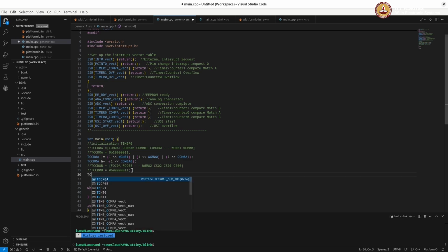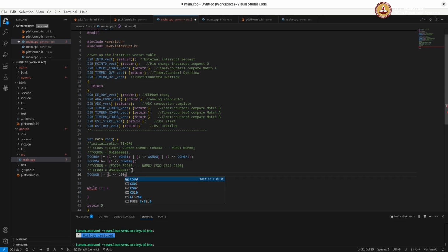So let me write TCCR0B. So I will OR it with itself, okay, and set CS01. This is one thing that I'm going to set.